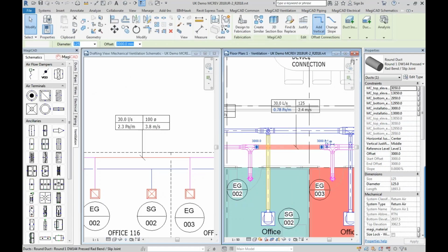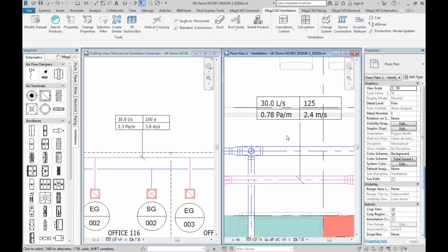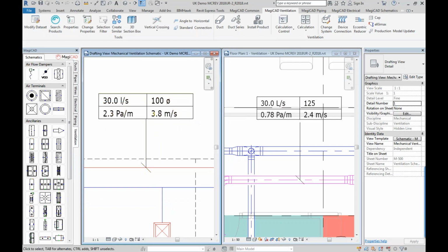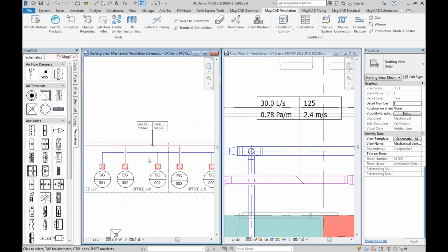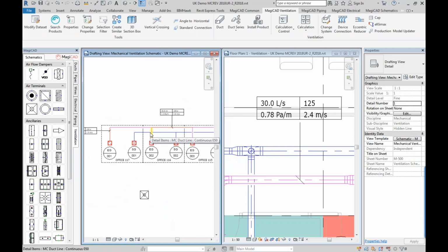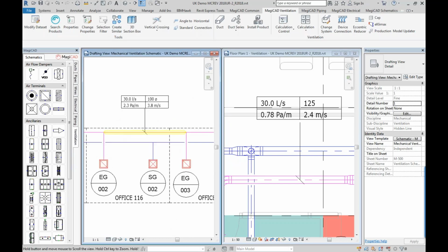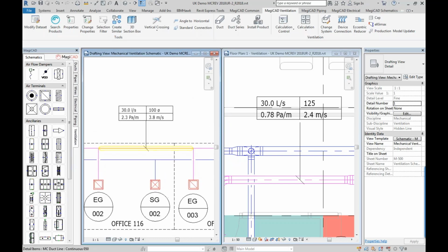So like I said, this is the time-consuming bit of schematics where that duct segment now has the same flow rate, but I've resized it, and now the diameter's changed, the pressure drop's changed, velocity's all changed. Traditionally, you'd have to go in there and change hundreds and hundreds of ducts, and then you might make mistakes, etc. But the whole point of this is one source of information that feeds all the other information that you wish to derive from it.